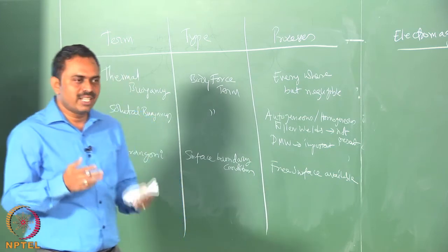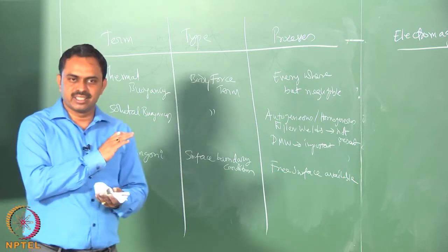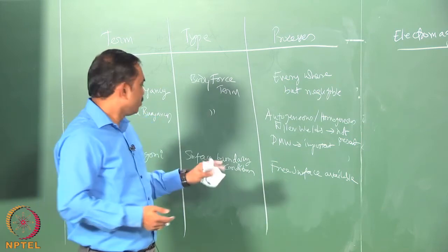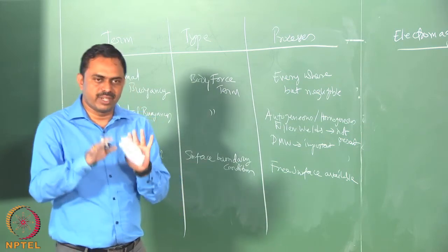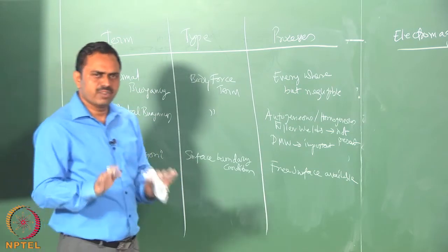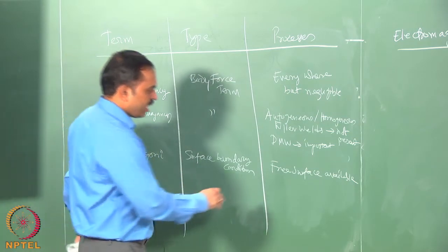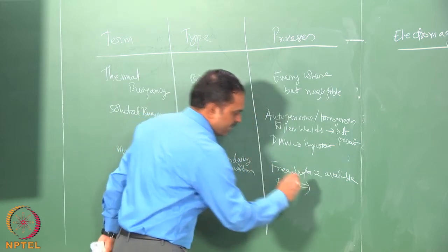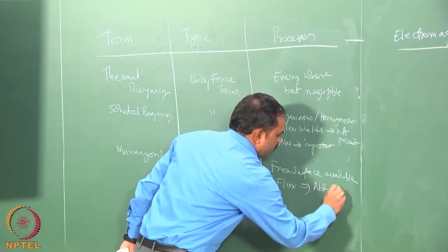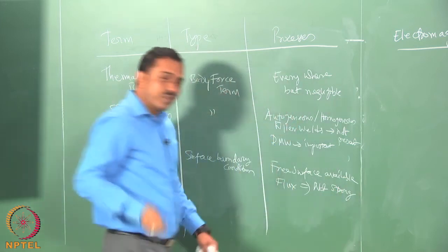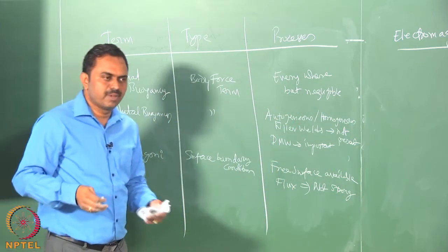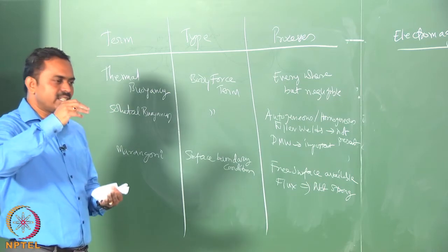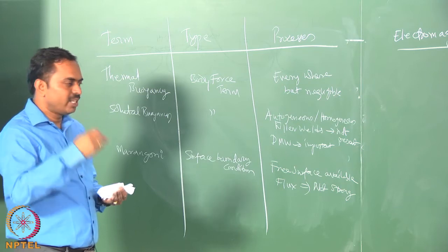So, which means that whenever the liquid melt pool is covered by a flux completely and there is no free surface of the liquid metal exposed, then you can say that the Marangoni convection is very much suppressed and not very strongly present, which means that if you have flux it implies not strong, and it is very strong, for example, in materials which are being welded where the temperature changes are very drastically changing from the center to the edge of the pool.